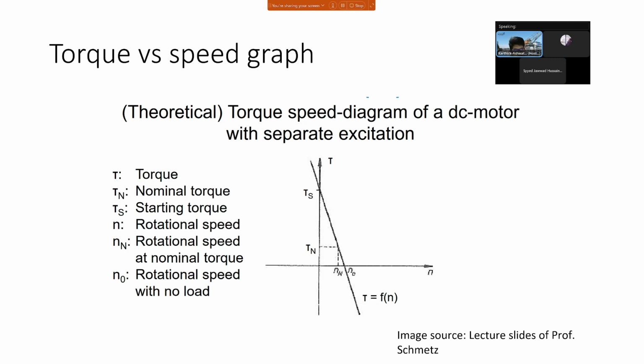Because for a fan, if you just connect this DC motor to a big fan, the power demand looks exponential. Let me show the torque demand first. Torque is proportional to n squared for a fan. So if you want a large range of speeds with this motor, you would not choose it, because the variability is too much. More and more torque is needed at higher RPM, but here it's giving lesser and lesser torque at higher RPM, so it's not a good choice.